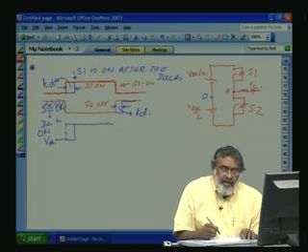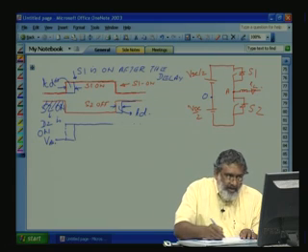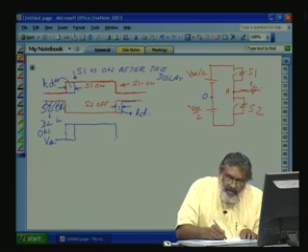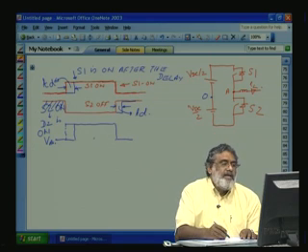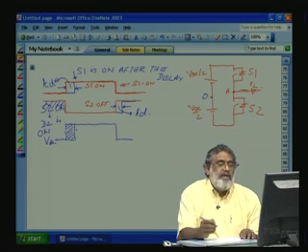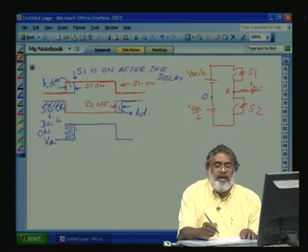Again, at this point, when S1 is off, immediately the diode will conduct, that is instantaneous. So, if you see here, for the pole voltage, this much area is lost due to the dead time. This much area is lost, correct?